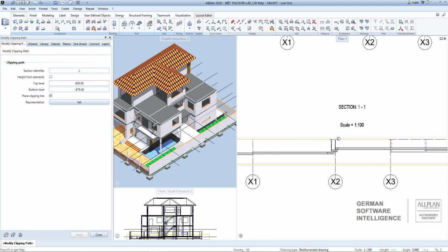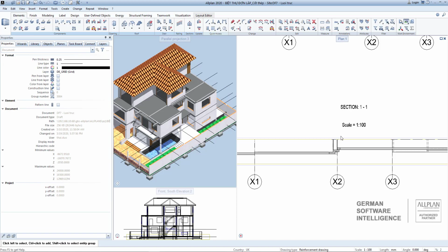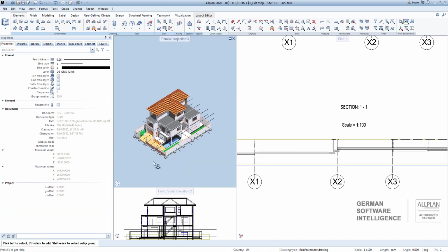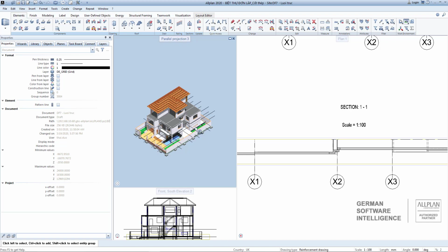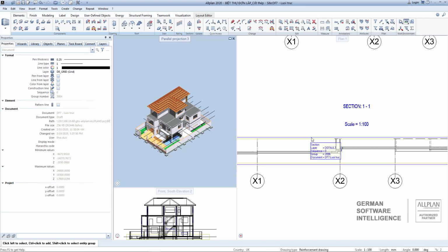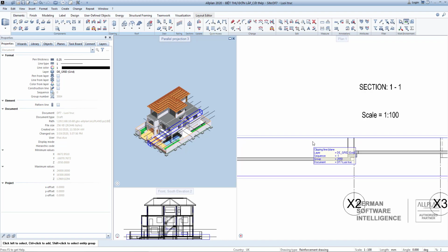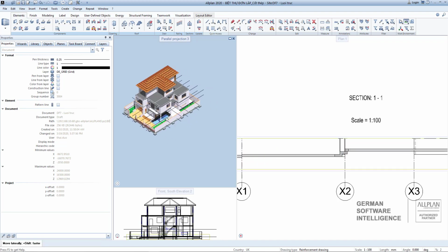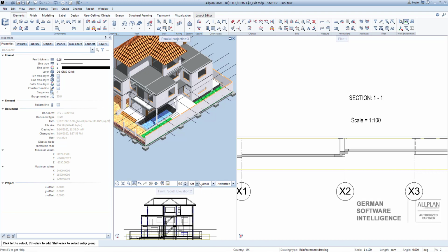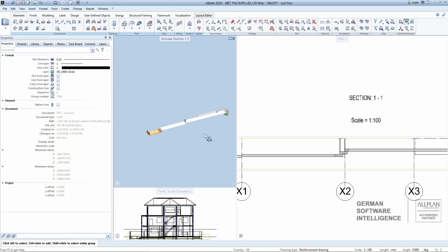And the last part I want to share about the section in today's lesson is the 3D display within a section. For a large project with complex and many components, if you only care about a small range of the building, you can look in 3D by selecting the name of the section. Then we can observe only the part of that section cut through, without having to filter or hide or show objects.